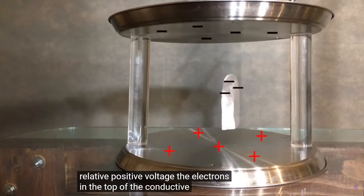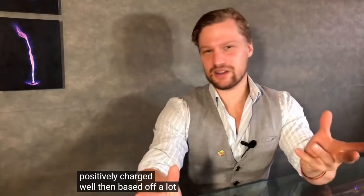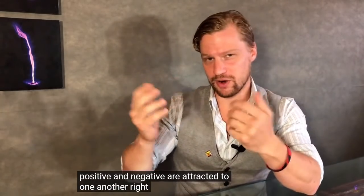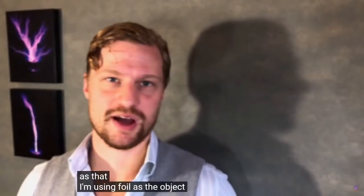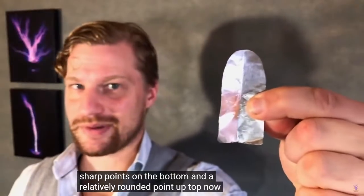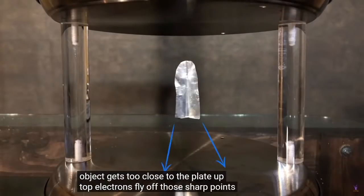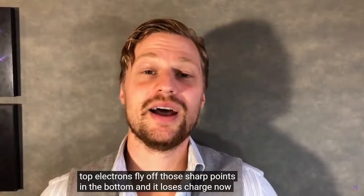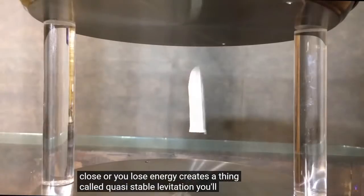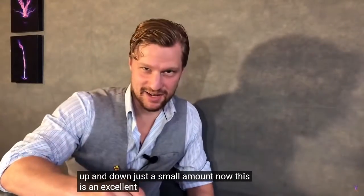Yeah. So What's Up in the chat is asking, how is this dude using 200,000 volts? Normally you would think that would be really dangerous. And of course, 200,000 volts can be dangerous if there is any amount of current flow that accompanies that static potential. But Van de Graaff generators generate a very high static voltage, but they will not deliver a whole lot of current. And the current is the actual electron flow that goes through it. For total power in watts, you consider current and voltage: voltage is measured in volts, current in amps, and you multiply the voltage times the current to get your power.